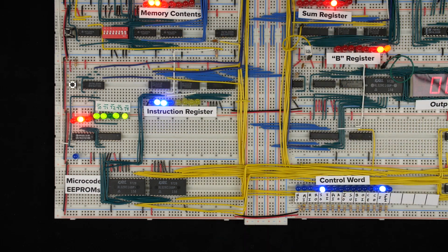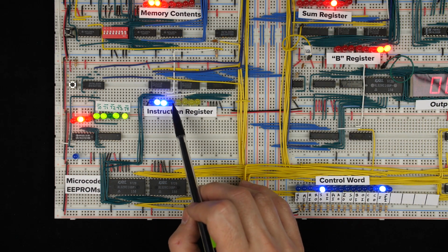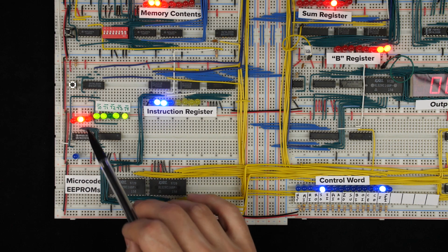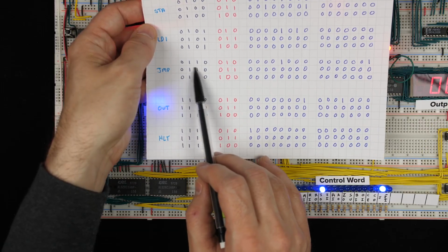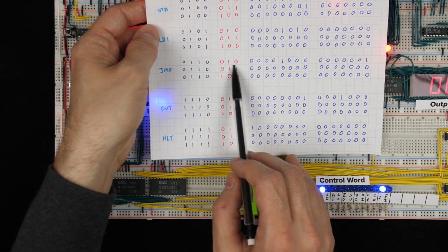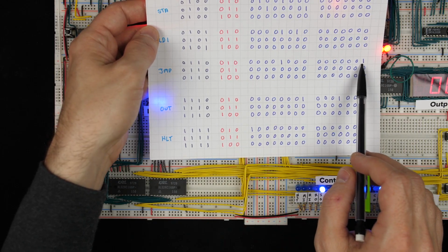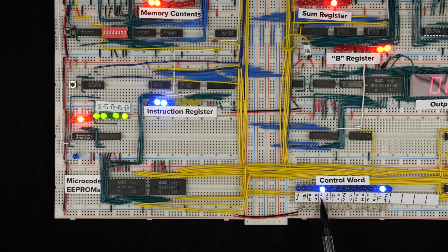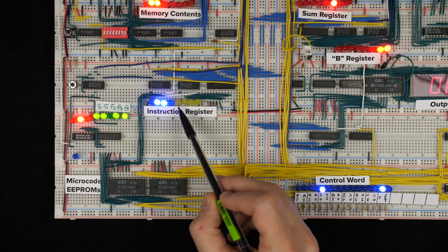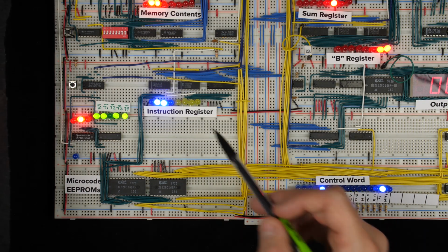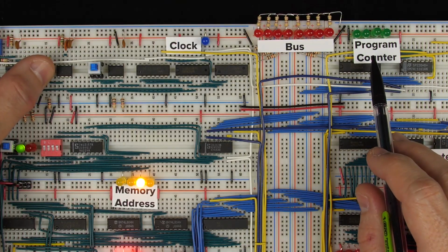So at step 2 now, we've got 0110 in the top half of the instruction register, and 010 is our step. Anytime that we've got 0110 as our instruction and 010 as our step, like we do, then the microcode EPROMs are going to output this control word here. This control word says take the bottom half of the instruction register and put that into the program counter. In other words, the next instruction executed will be at address 0, because that's what's in the bottom half of the instruction register. If we execute that, you can see this 0 goes into the program counter.